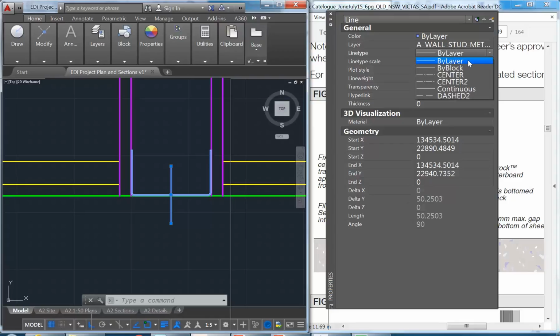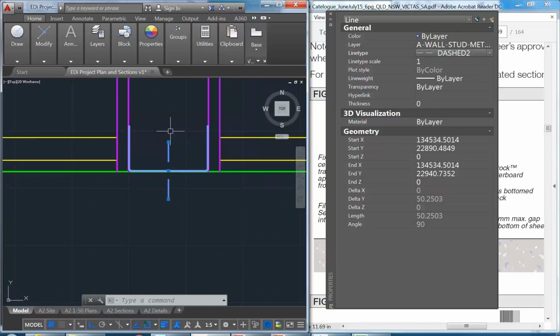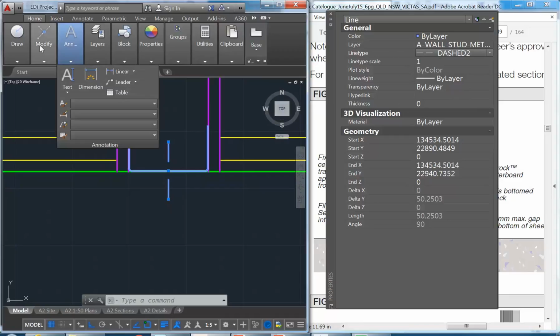You can change the line type to something different. So I'm just going to try and find one that you can actually see. Here we go, so -2. I'd actually want one of these others, so centre 2 is what I want, but I'll come back to that in a minute. But you can see there that's changed the line type, but it's still on this layer. So you can override any of those properties. It's usually good to leave them on by layer, because as we've been doing it, you can change the colour, line weight, and line types most easily just by going and changing the layers.